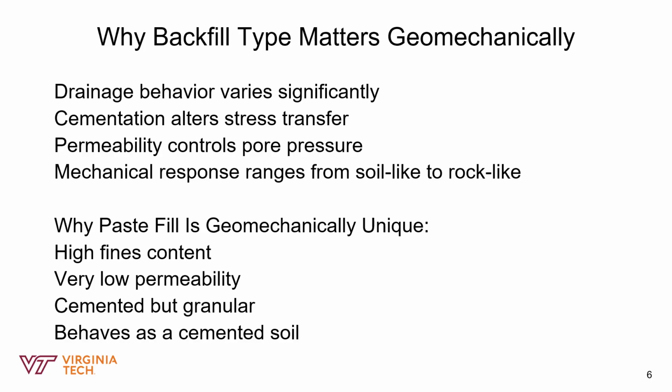So why does the specific type of backfill matter to a mining engineer or a geotechnical engineer? Why can't we just treat all of them the same? Well, the answer is that the physics change depending on the material. On top of the list, we have drainage. Some backfill lets water pass through instantly, whilst others trap it.